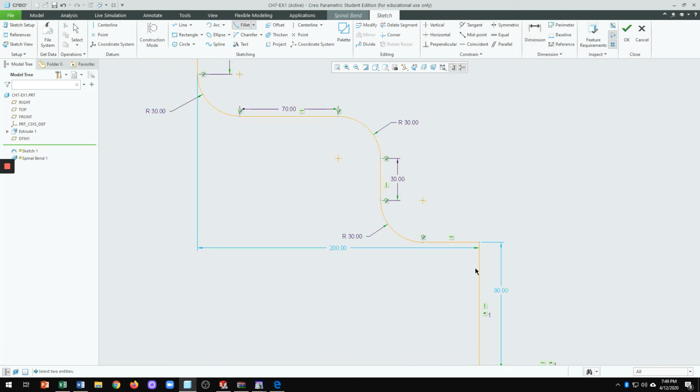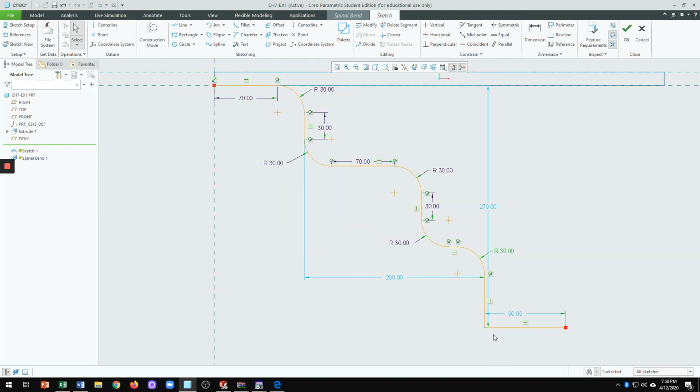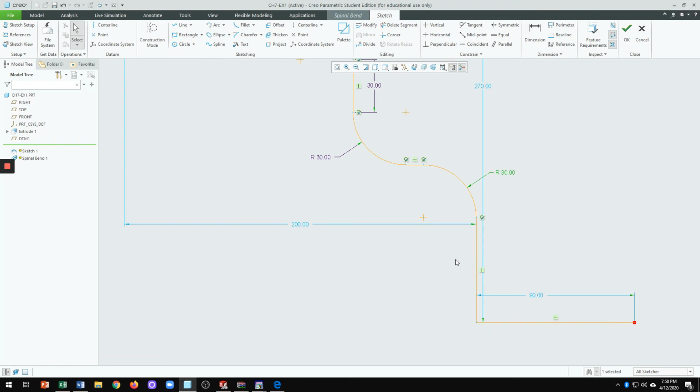Let's put more fillet radius in here. And as you walk through this, just give the dimension. Later on it should be ready to go, because otherwise you have to go and fix a lot of dimensions, which is a headache. So, fillet radius, one more in here.